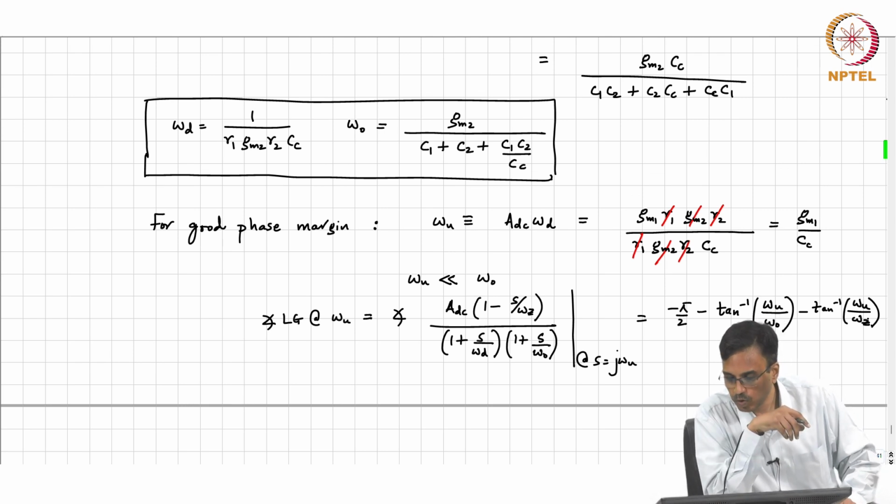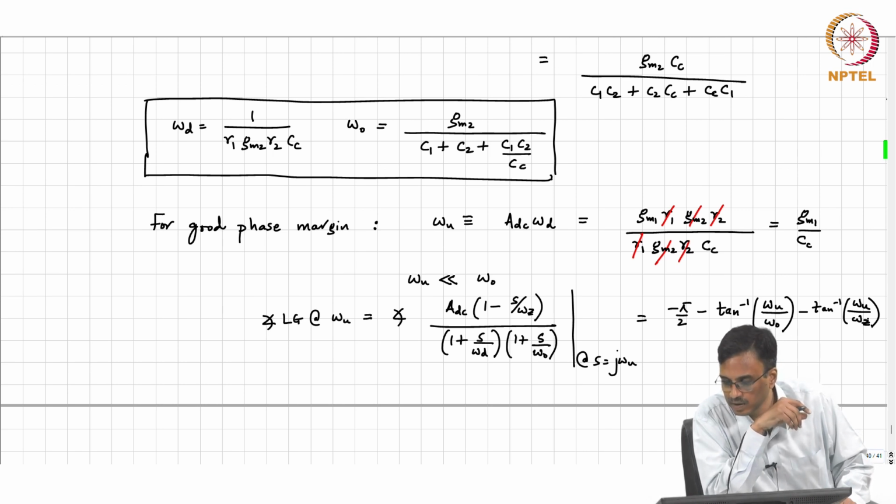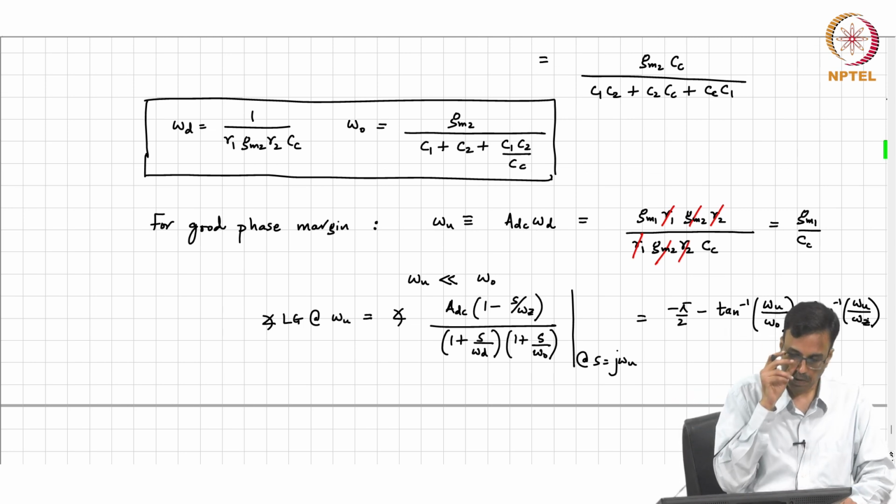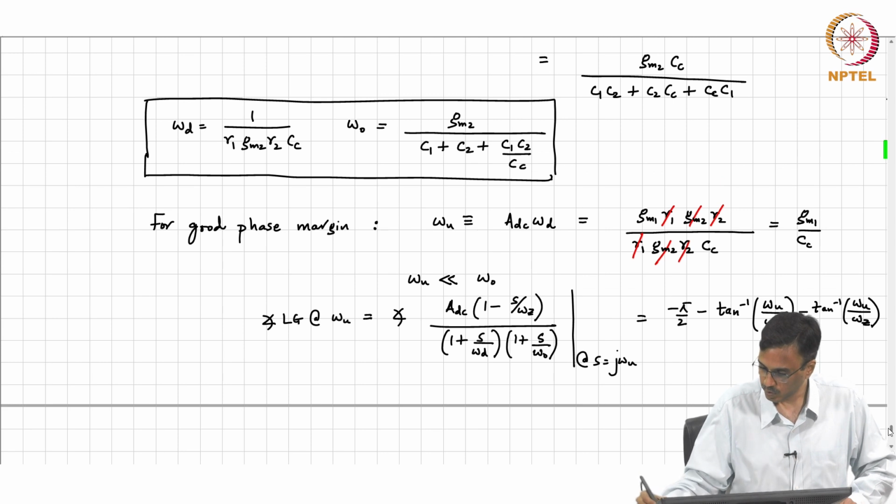All right. So, a quick question: does the feed forward zero hurt or help the phase margin? It hurts, right, because it is in the right half S plane.